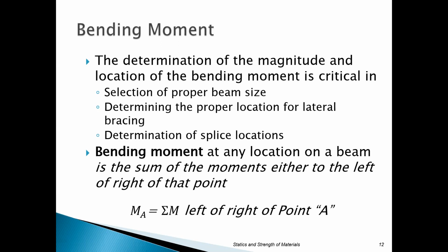So again, all you're going to do is a simple moment equation. It's just a force times a distance, and we can determine the point of maximum bending moment for those values. Again, we'd have to look at simple beams, solving their reactions, and then doing a moment. Remember, moment is just a force times a distance. And if you're using distributed loads, you're going to have to think about that a little bit differently, because you have to calculate the point you're dealing with and then where that load is located.